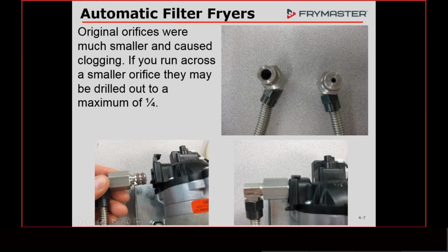The thing of it is, though, we were probably pulling these orifices out to put in the new pump that was ordered, because we got voltage to the pump and it didn't come on, so we ordered a pump. We changed dozens, I mean, probably more than dozens of pumps for that reason. One of the biggest reasons was that when we originally made these fryers, the orifice size that was spec'd out was that size there. I don't know exactly what size that is, but it's too small.